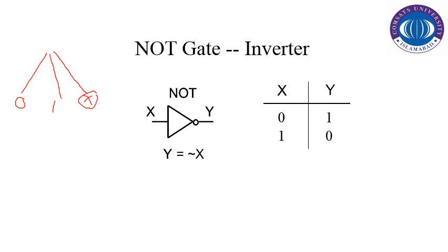So let us assume that we've got a Boolean variable A, so that you don't confuse that with that. This is the value that any input or output pin in a digital circuit can have. And the fourth possible value can be the Z state, that is the high impedance state. Normally the Z state is mostly utilized in tri-state gates, which we will discuss later on in our second session. Since we are starting with our basic definitions, right now I'm skipping the definition for the X and Z literals. In later stages, I will definitely define these as well.